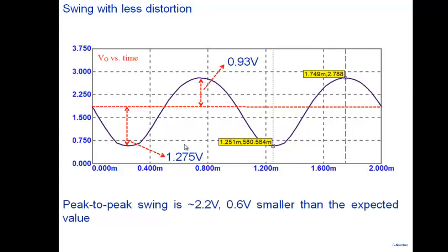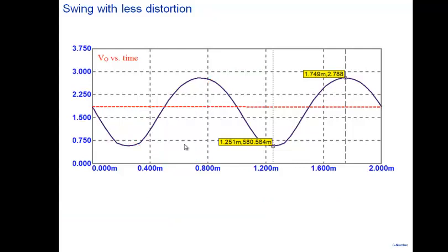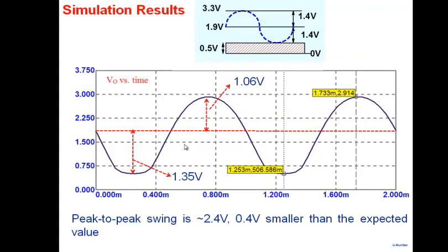Okay. So the issue is, how large a swing do you think you can get? How should I answer that? For this amplifier, what is the swing that you can get? Would you call a swing of 1 volt what you can get? How should I define the output voltage swing? Peak to peak. Fine, I can define peak to peak, but what is this amplifier capable of? How much peak to peak? Is peak to peak 2.2 or is peak to peak 2.4? What is it? What kind of a peak to peak output voltage can this amplifier get?